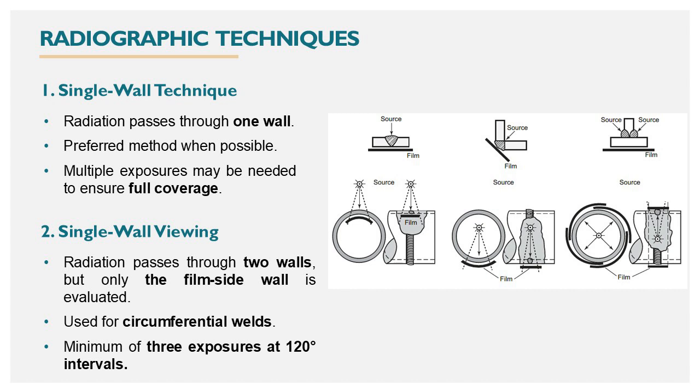Radiographic techniques. The first radiographic technique is the single wall technique. Radiation passes through one wall. Preferred method when possible. Multiple exposures may be needed to ensure full coverage.